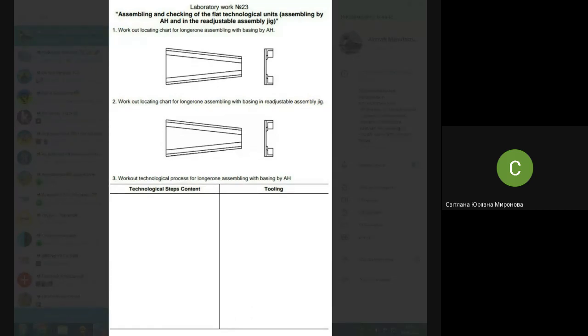And next, in future, if we have such an opportunity when we study it, I will show you that the statement that assembly holes are cheaper is not correct, because it depends on how many items you're going to assemble in a jig or by assembly holes. Above all, assembly holes, the first method, the one which you're going to reflect here, is not so accurate with respect to the assembly jig. In an assembly jig, you do something more accurate.